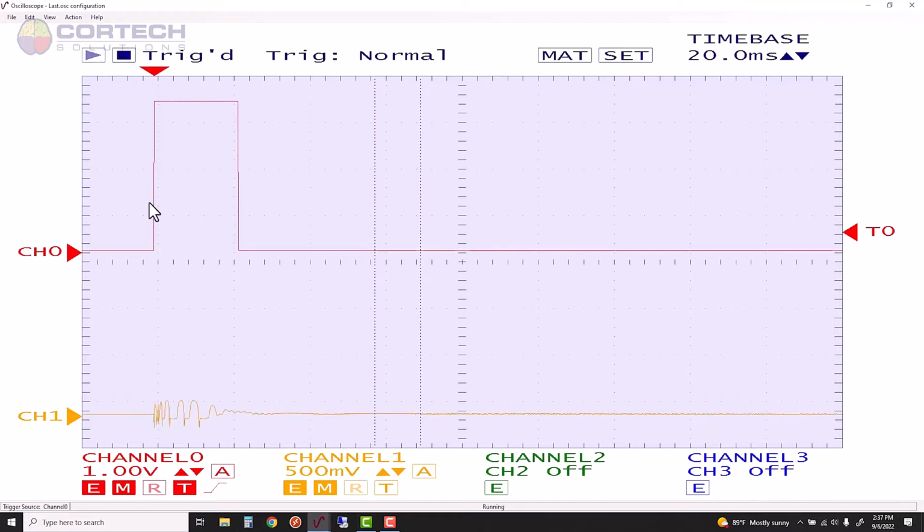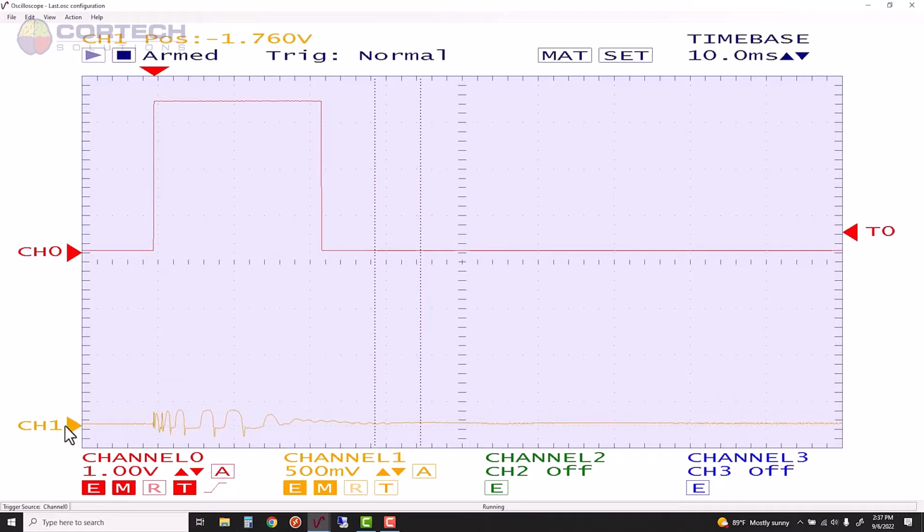And you'll see on the top, we have channel 0, which is the digital output that is being produced by Triggy in response to this analog input. So our time base is 20. Maybe that's a little too long. I'm going to reduce it to 10. And we can see a little more clearly the relationship between the audio and the TTL output. If I drag this up, by clicking and dragging on the triangle, then you can see the temporal relationship between them more clearly.